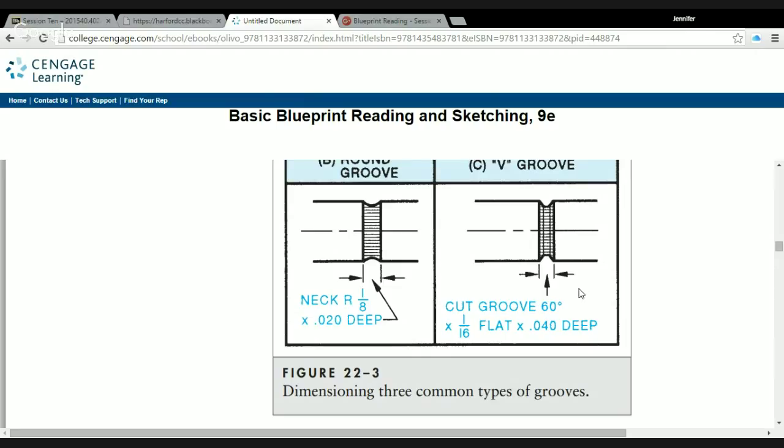Remember up there when we did chamfers, they were just showing you the 30 degrees, and we flashed back to countersinks and said when we do countersinks, we do the entire angle. Well, the entire angle is coming out this way and coming out this way. So from 1/16, we cut in at 60, 40 thousandths deep. We end up with a little flat area here after we go in 40 thousandths. It's a little more of a complex cut.